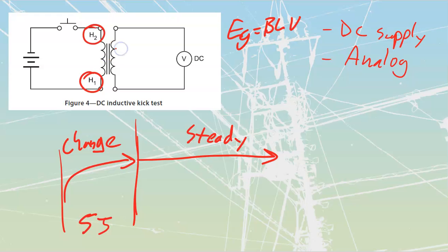So once again, I would have started by walking myself over to one side of my transformer, standing on that side of the transformer, looking across, labeling that one as H1. Once I had an H1, H1 had to be positive. So that was how I started the test, is I made this circuit. You can do this off of like a car battery or something.